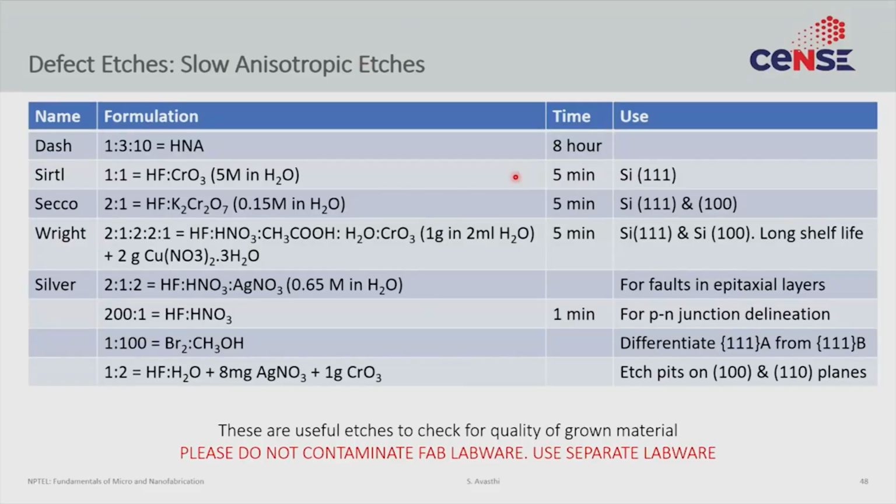Using a defect etch. The details are convoluted, and we shall not discuss them too much, but the basic fundamental is that we use the anisotropy of the etchant. What we say is that in and around the defect, the lattice is unhappy. Because the lattice is unhappy, it can have a slightly different etching rate at the defect site than at the rest of the bulk crystal.